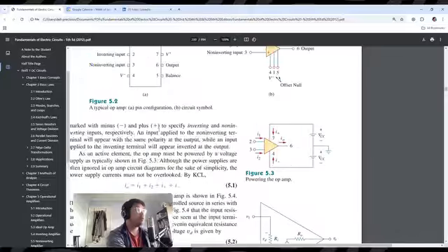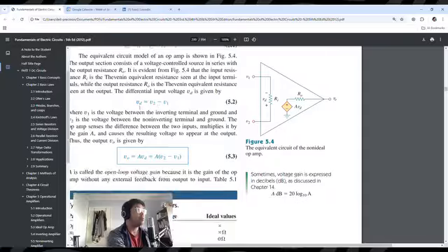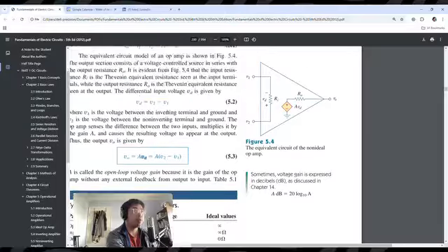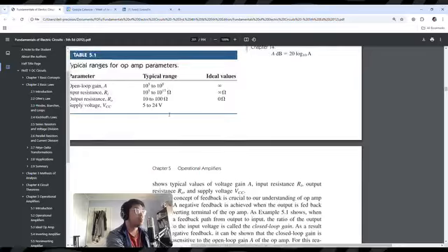If we look over here, we see that the difference between the non-inverting and the inverting input is a set resistance here, V2 minus V1. We don't really need to know too much about that right now because we're going to be going to LTspice and hand calculations later. V out equals A, the amplifying factor, times VD, or the difference between the non-inverting input and the inverting input.